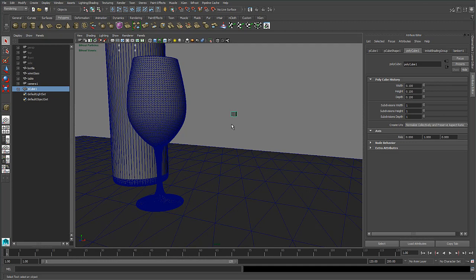Now, if you've got to scale everything down, which we're about to do, just remember that there's a scale factor involved, and as long as you reverse that scale factor at the end of the process, you can scale everything back up to real world scale once you've completed the Bifrost simulation. That'll make sense a little bit later on once you're familiar with the whole process. So let's go ahead and use this cube here. What I'm going to do is put in 0.3 by 0.3 by 0.3, and that's going to be our reference cube, remembering that the wine bottle is 30 centimeters.